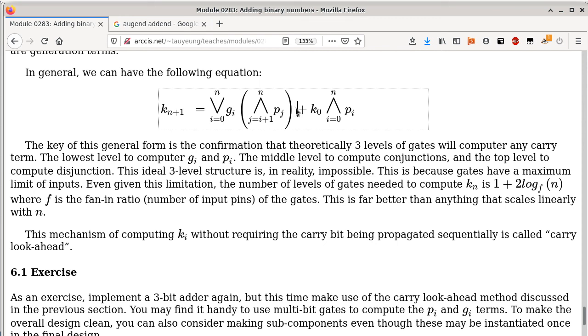A 32-bit adder is going to take the same amount of time as a 64-bit adder. Is it going to use up more silicon? Oh yeah, it's going to use up quite a bit more silicon, but it still takes the same amount of time. So all modern processors make use of carry look ahead, which is this mechanism, instead of carry ripple, which is a very simple concept to explain. It works, but it is not practical because it takes too long. So are we good so far?